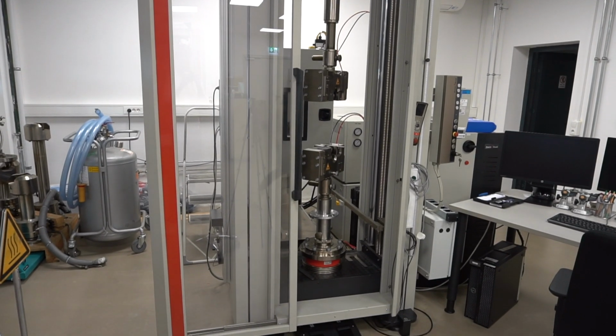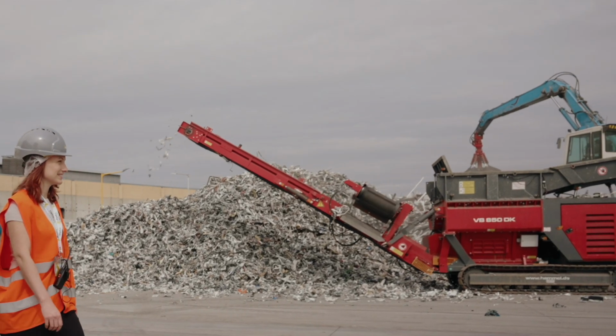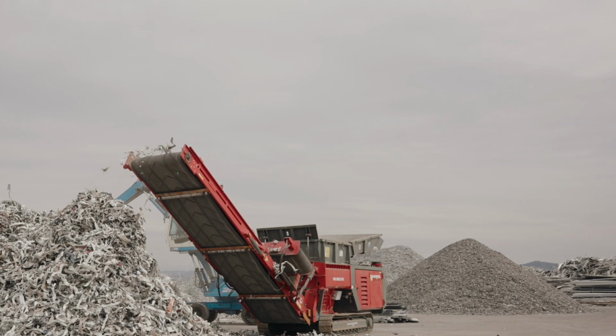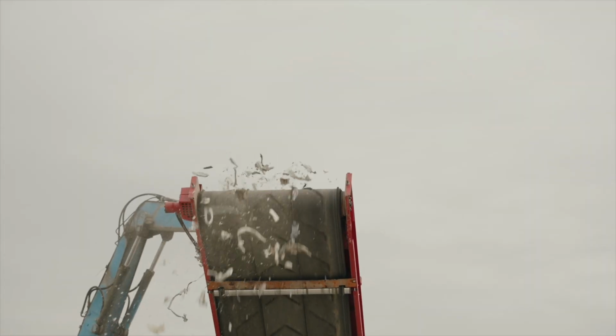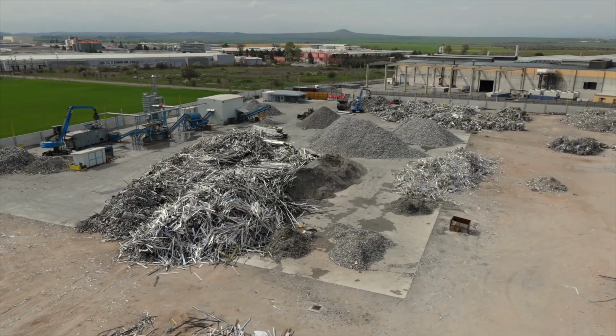So the ultimate goal is, of course, to have an alloy that has a maximum amount of scrap and a minimum amount of primary aluminium. And with this approach that we have, we can design an alloy with the highest amount of scrap. We know how the scrap and the special impurity elements are included in the microstructure and what the effect on mechanical properties is. And as soon as we understand what's really happening in the material, we can potentially even put more scrap into the alloy that the industry really needs.